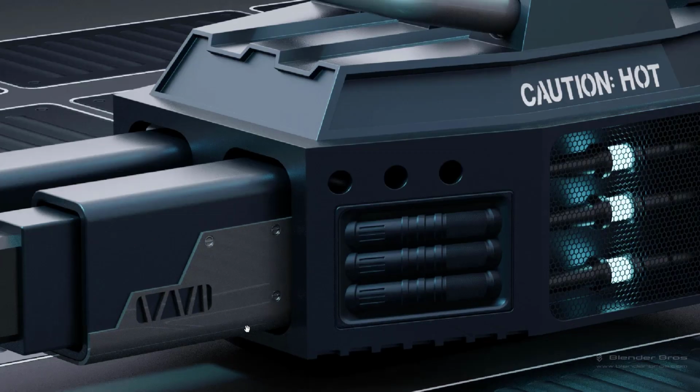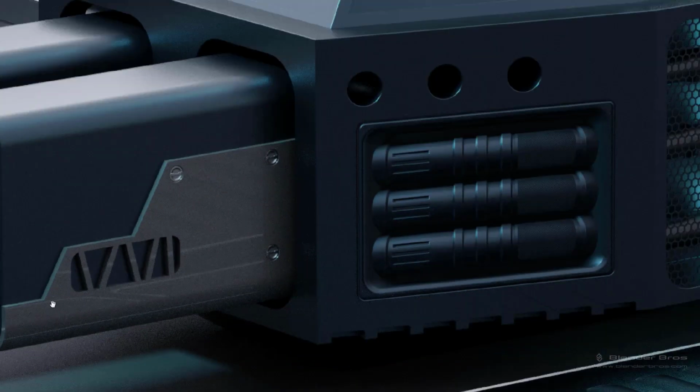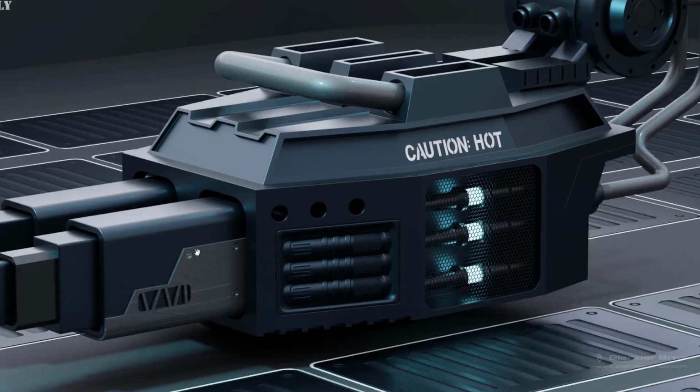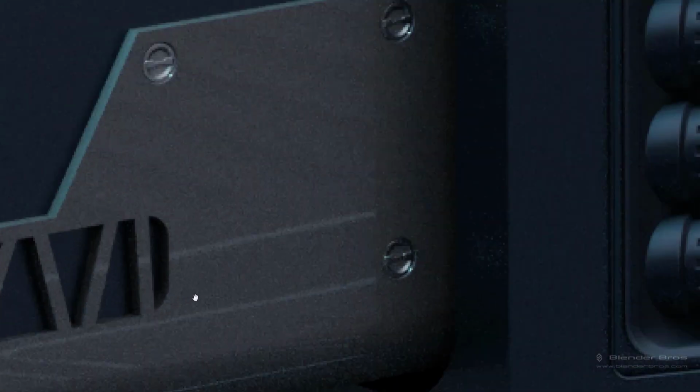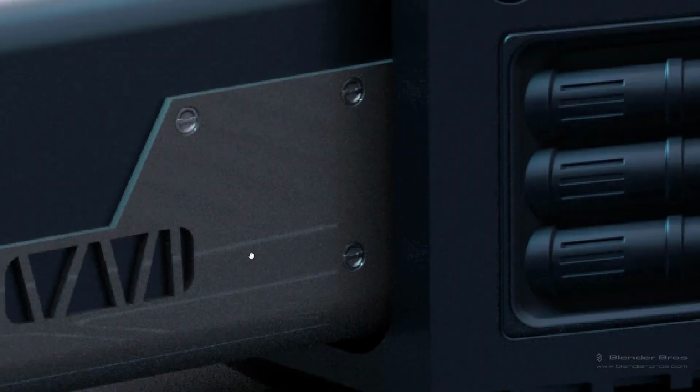Next thing, if we zoom in, we have these weird visual artifacts right here. Not sure where these came from. I'm going to assume maybe something with your topology, or maybe you had a duplicate piece that popped in, or I really don't know what this could be, because this is your render, right? But it looks like there might be an overlap, so make sure all your backups are turned off in rendered view. Otherwise you might get these weird overlaps going on like this.